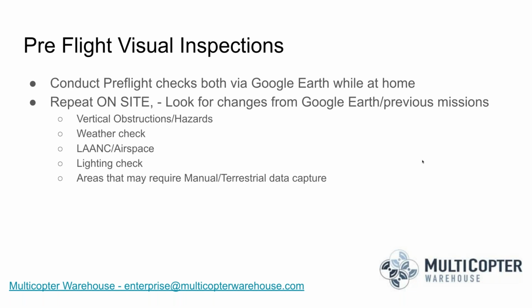And then also do a lighting check to make sure there are no areas of your project that may be encountering what I'll call heavy or dark shadowing. If the area is not well illuminated, it's hard to get good quality images of it and it won't map well. And then lastly, consider what it is you're trying to map and model.